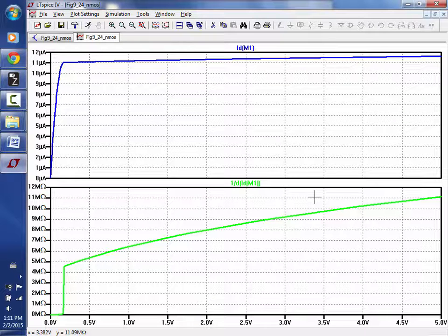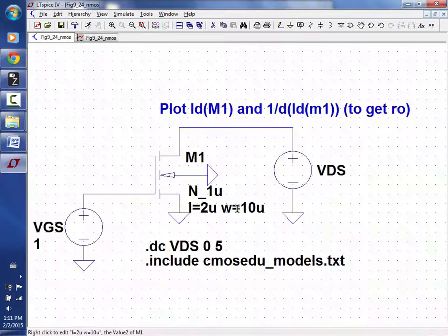Okay, if that's the case, then perhaps your .include CMOS models got corrupted, so I would download those again. It might be using the default values because it won't tell you if it can't find the models, in, it's called NMOS or whatever you have here. It might use a default model for the value and then it's going to give you totally whacked out results.